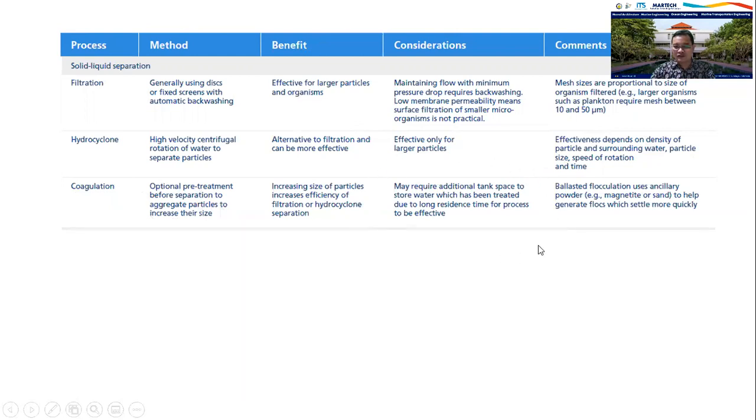But there is a consideration: it may require additional tank space to store water, because with coagulation the particles become solid and get bigger, so the sediment will get bigger.